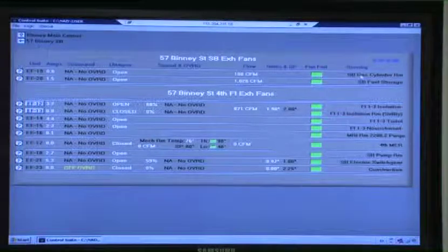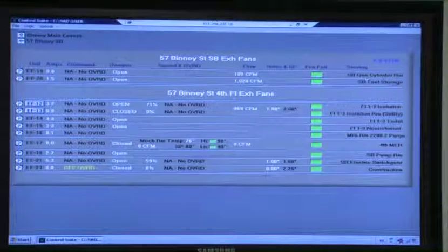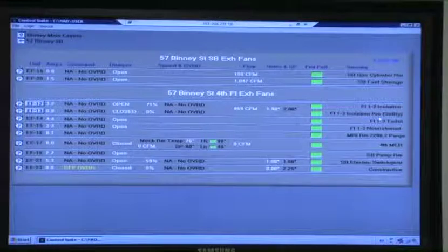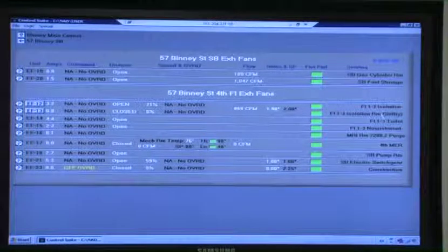One other thing I don't see down here, Jamie, is room numbers. I don't just want sub-basement gas cylinder room. It should be a BB number, whatever it is. All these room numbers, so they understand that exhaust fan 7 is serving this room. There could be multiple room numbers actually. It all depends.